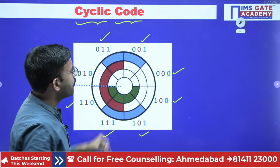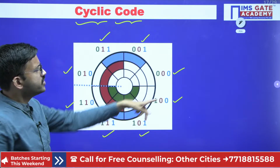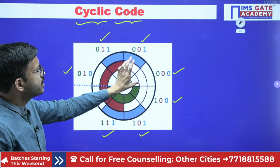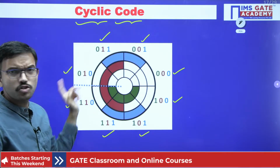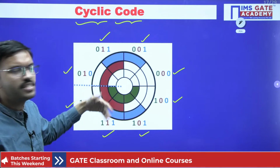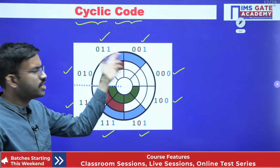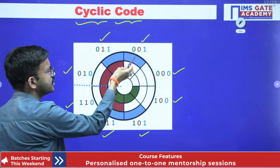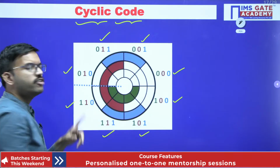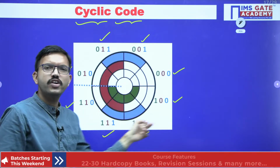what will happen? From one sector to another sector, if you are using 3-bit unsigned code, at some places only 1 bit has to complement, at some places 2 bits have to complement, in the worst case 3 bits have to complement. But if you are using gray code, from one sector to another sector only 1 bit is changing. It is easy. Or you can say that there is a uniform delay.